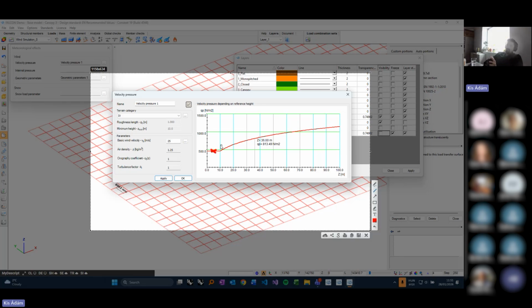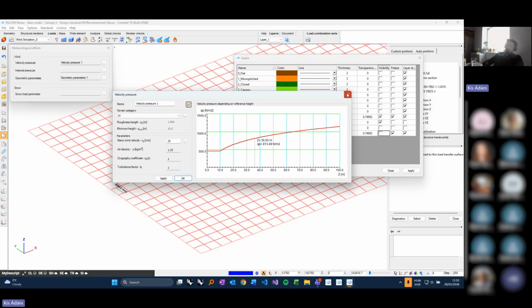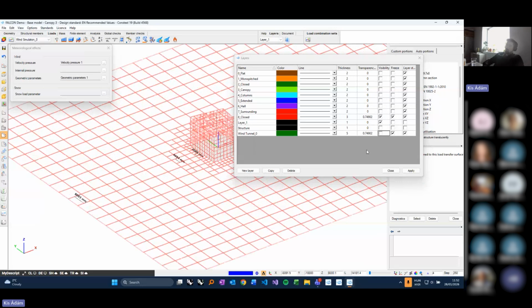So we have an 8 meter mesh size, then 16 meter, and we will have a somewhat linear profile, but still close. If my mesh size is higher and I end up with maybe a 32 meter inlet size, you can imagine that the actual wind profile of the Eurocode will be lost. So this is how we are trying to recommend those initial values during the simulation, because these can lead to more proper results, even if they maybe take a bit more time.